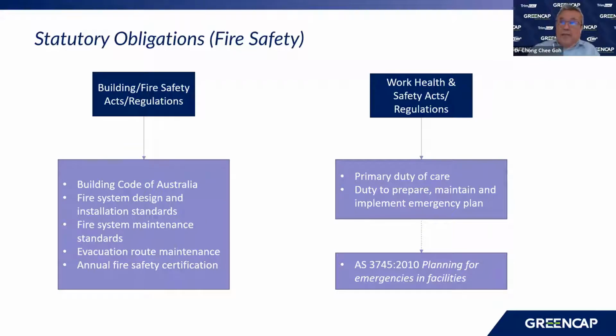Yes, thank you, Brad. I think to illustrate this, it's best to imagine there's a Christmas tree in front of you, and sitting on top of that Christmas tree is your Building Act, and it just flows down from the Building Act that calls out the regulation. So in terms of building construction, the Act will call out the regulations, and the regulation will then have a certain aspect that you need to meet. That would be addressed for the building construction in the Building Code of Australia, which is the BCA. And then the BCA will give you a minimum requirement in terms of how to achieve the fire safety objectives by having certain design parameters to be included.